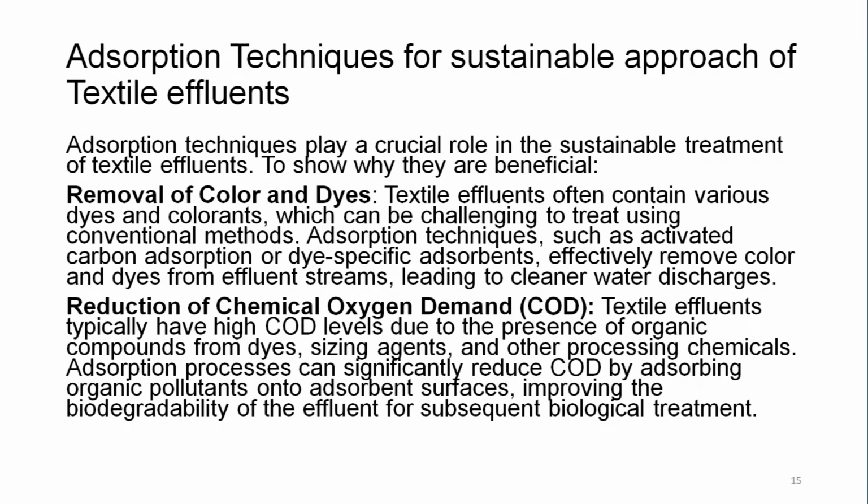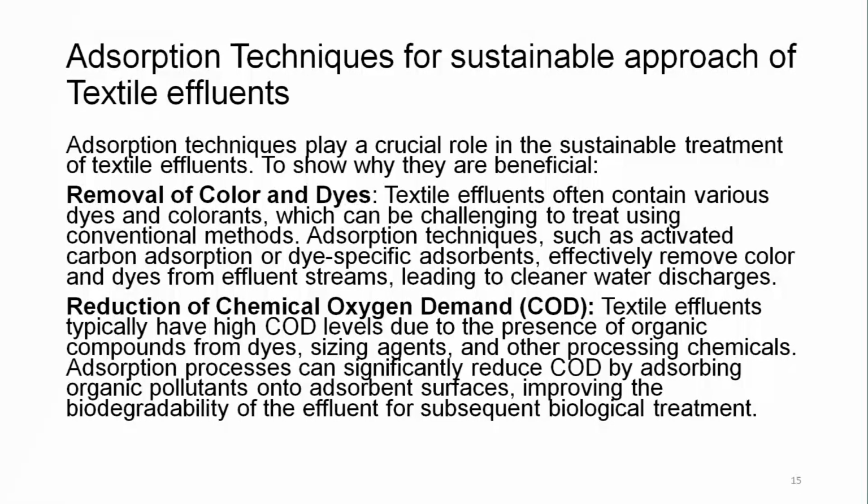Textile effluent often contains various dyes and colors, and we have seen this from lecture number 1, which can be challenging to treat using conventional methods. Adsorption techniques such as activated carbon adsorption or dye specific adsorbents effectively remove color and dye from the effluent streams, leading to cleaner water discharge.